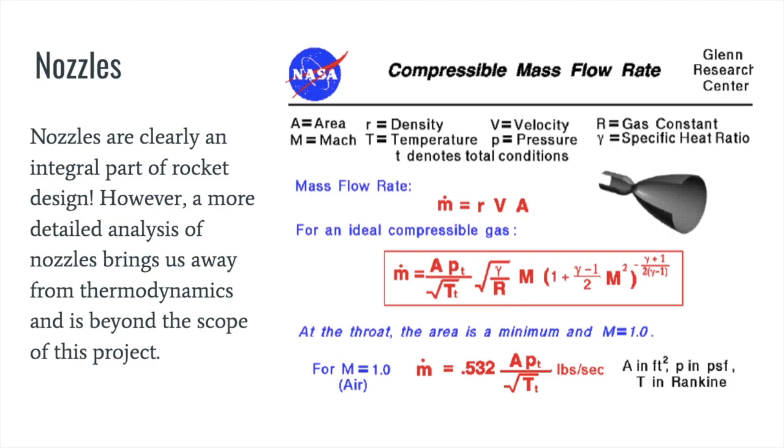When you look at this equation, together with the relationship between thrust and mass flow rate shown earlier, you see how important nozzle design is for rocket performance. The smaller the nozzle, the higher the pressure and the greater the thrust, but the quicker fuel will be spent. If the pressure is too great and exceeds what the combustion chamber is capable of handling, the rocket will be a bomb. A larger nozzle can increase how long the fuel will burn for but decrease the thrust produced.